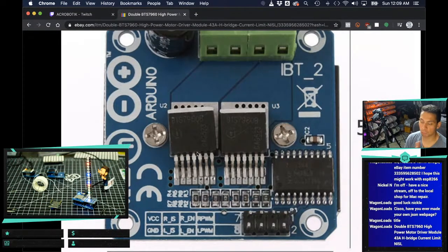And I've seen a lot of folks buy these chips, the breadboardable version or a little breakout board, and try to fiddle with stuff. And it just gets a little hairy. But this should be fine. Your biggest worry is going to be burning them out, and not because of current, which you have to check, because you have your average current and you have your spikes once you flip the switch on, and that might blow them up. But these guys will get insanely hot and they might fail because of how hot they get.